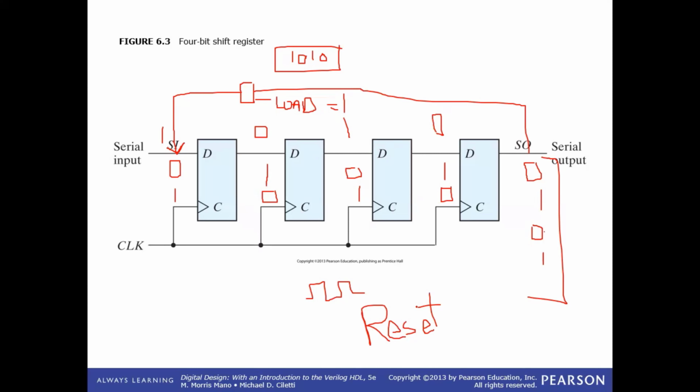Okay, sir. Okay, so there's one thing that is really important, and I want all of you to be very attentive. I did not play with the clock. I could have retained the output by placing AND gates at the clock, by suppressing the clock, and by maintaining 1010 at the output.